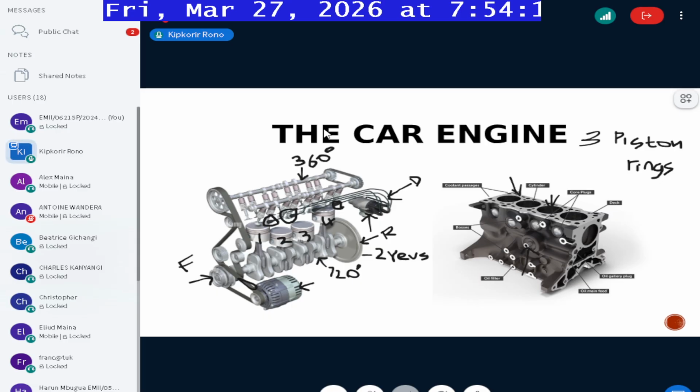And oil is a very heavy hydrocarbon. It's a very long hydrocarbon chain, which means it does not break down very easily even when you burn it, especially at the temperatures found in the internal combustion engine. So you get a lot of dark soot and darkening along the piston crown. It is usually a pointer to worn out piston rings.